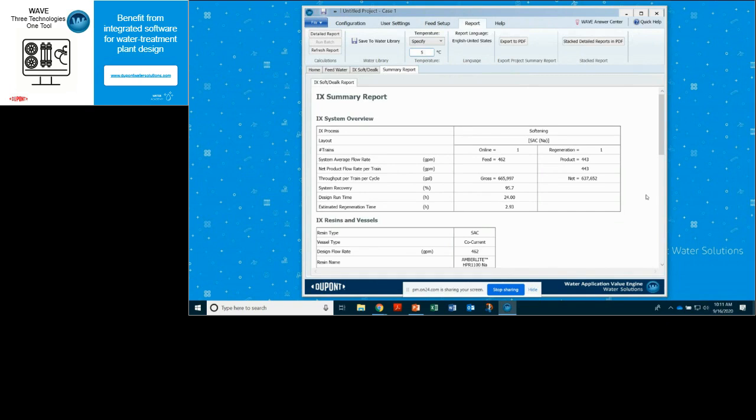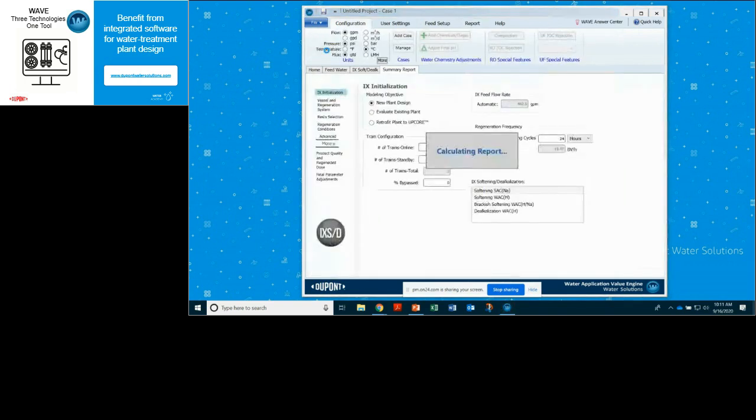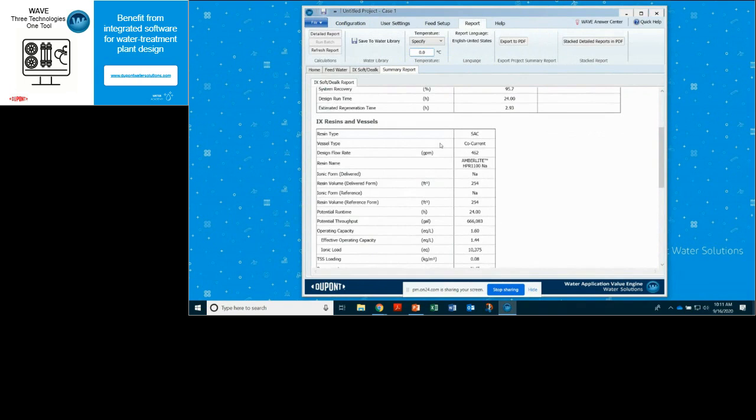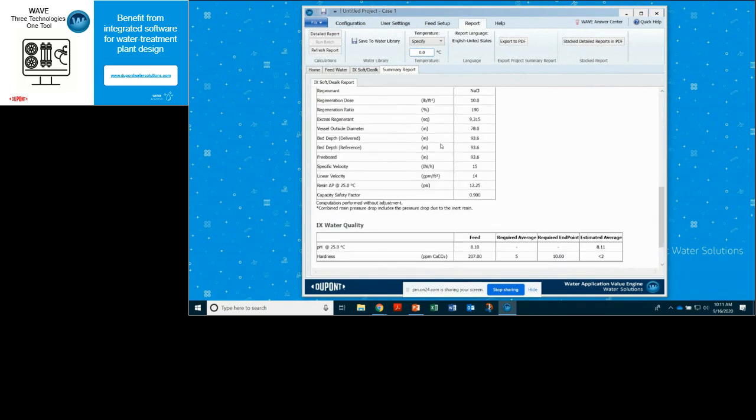And in this case, the minimum temperature is already pretty low. It was about 5C, so we could either select minimum up there or specify the 5C and then refresh the report, and we can quickly look at what the pressure drop estimate is in this case. All right, so as you scroll down, I would expect, Garth, that we'd see some shift in the...